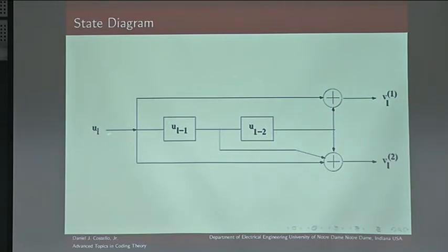and there can be an adder here, okay? And then what comes in here is not just this input bit, but this input bit plus whatever was fed back, okay? You can also have realizations of encoders where you'll have inputs into the middle, maybe an adder here where an input is put in there. And then this simply shifting down of input bits would not necessarily correspond to the state transition. But in any case, you look at the encoder diagram, you can always figure out what the sequence of states is going to be.